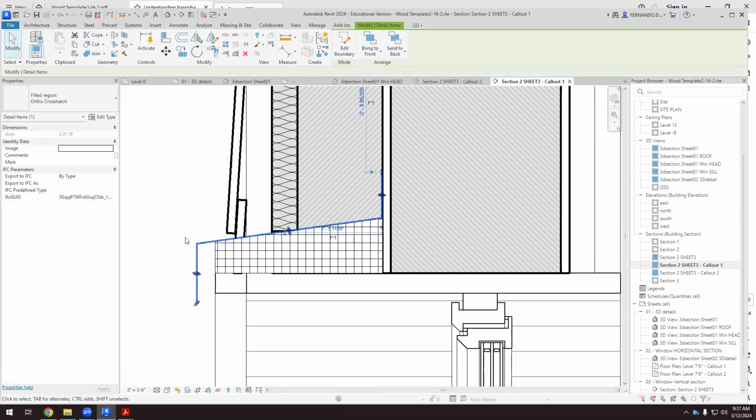I have created these flashing elements to lead the water out of the building. And I created this to create the slope. So it can be something made of foam. I think that would be the right thing, something made of foam with that slope, so that we can lean the flashing on it, and then we can get rid of the water.